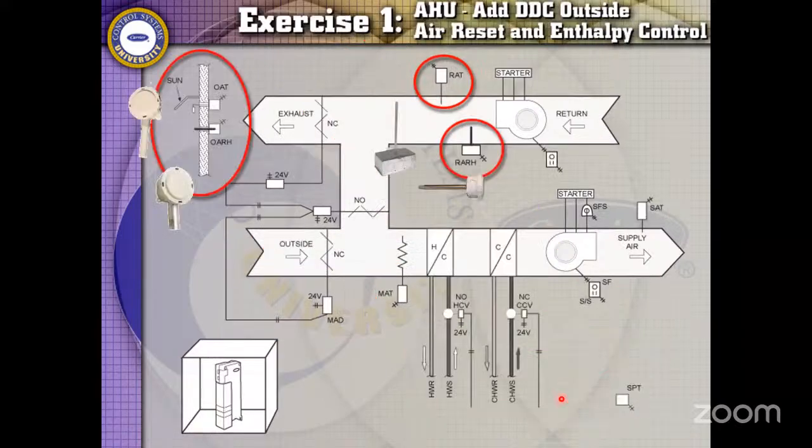I'm going to add outdoor air temperature sensors on here in order to control the economizer free cooling mode of this thing.